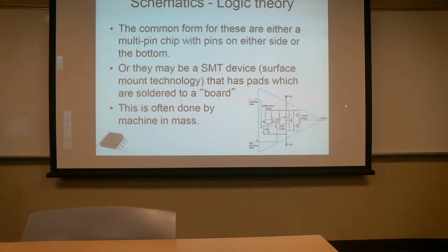But ultimately, the idea here is the top one, if a negative goes in, the output will be high. Or if a low goes in, the output will be high. If a high goes in, the output will be low. So it inverts the signal, it reverses it. On the lower side, it's called the non-inverting input. That input, if you use it by itself, the unit acts as a buffer.